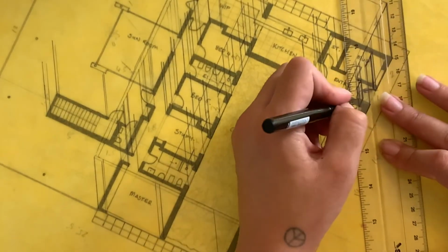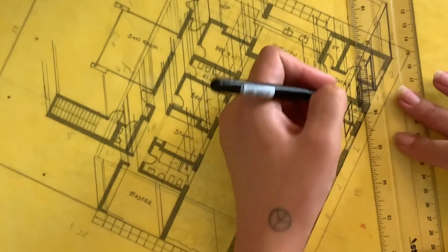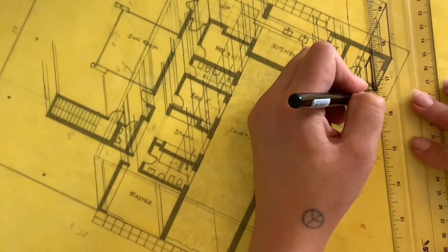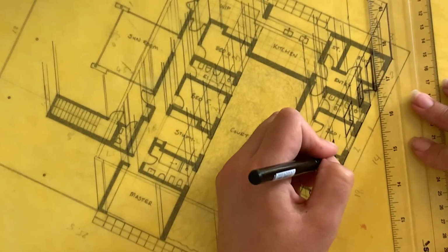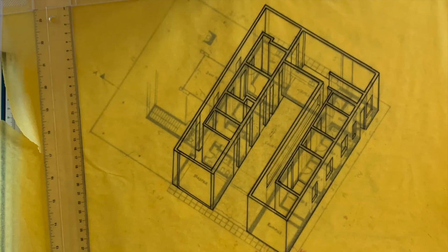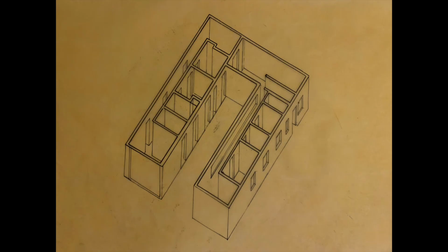The thickest line weight will be showing all of the wall planes where they've been cut through in the floor plan, and that will be done in a 0.6 pen. This is a very basic axonometric, and you can keep detailing these kind of drawings up, showing the relationship between planes, exploding it in diagram, and also showing structures of materials and textures if you would like.